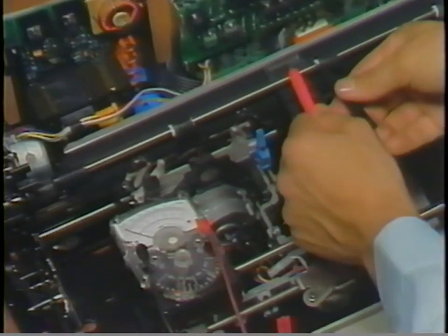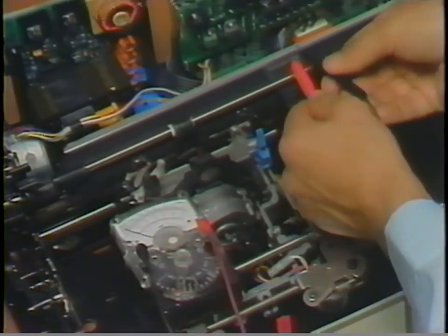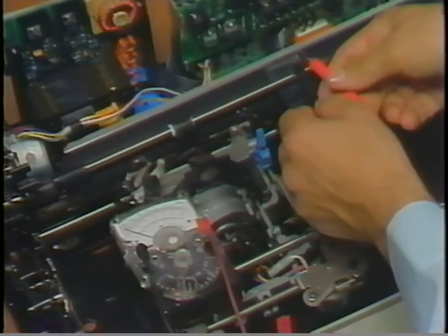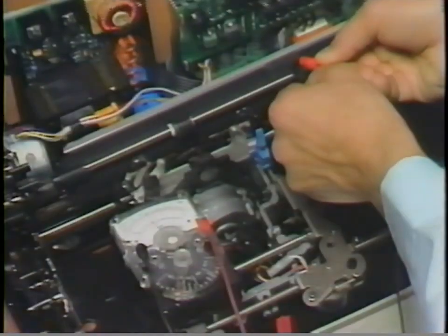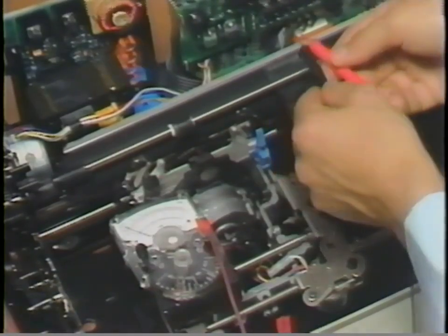To check the homing LED, measure the resistance of the LED in both directions. Using the ×1 k-ohm scale, put the common lead on pin 10 and the VOM lead on pin 9. The meter should not read continuity. Next, reverse the meter leads on the connector pins. The meter should now read in the mid-range on the ohm scale.